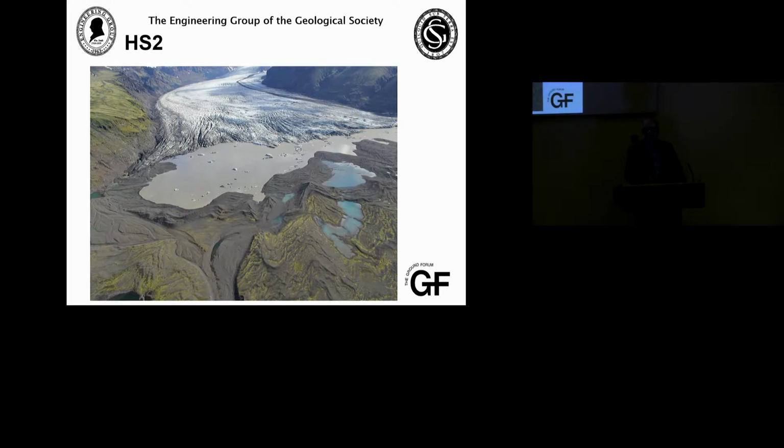It crisscrosses a terrain where sediments have been glaciotectonized. They've been shunted up in a series of thrusts and ramps and folds. We then have a large area of a glacial lake. We have icebergs rafting material across, depositing it in very fine-grained sediments. We then have the actual ice margin itself. We have material being deposited underneath the ice, material being deposited from on top of the ice. The ice sheet then retreats, and that's the terrain that we've then got to interpret with boreholes.